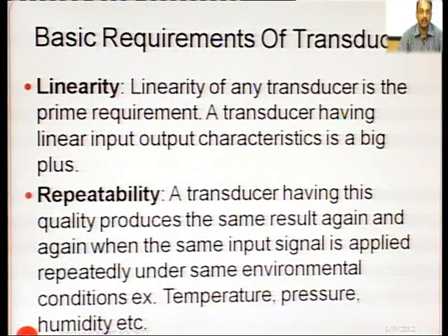For any type of transducer, there are some basic requirements. First is linearity. Linearity of any transducer is the prime requirement. A transducer having a linear input output characteristic is a big plus. Second requirement is repeatability. A transducer having this quality produces the same result again and again when the same input signal is applied under the same conditions, that is temperature, pressure and humidity, etc. That means there is no variation in the output.